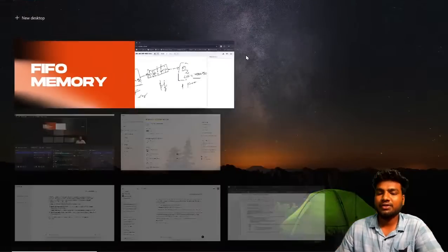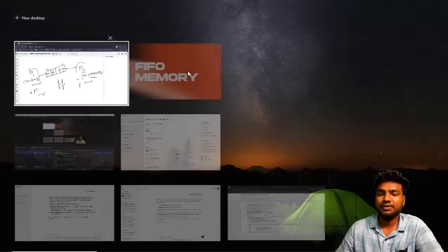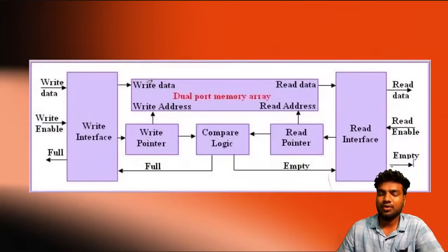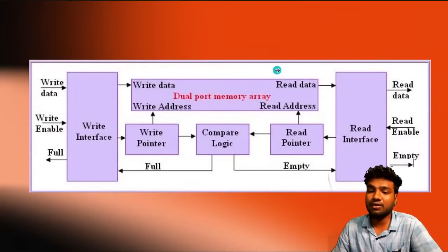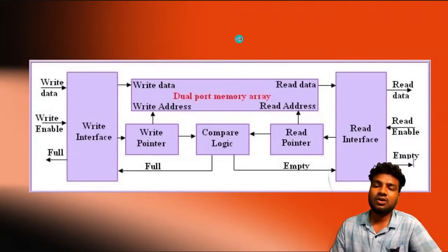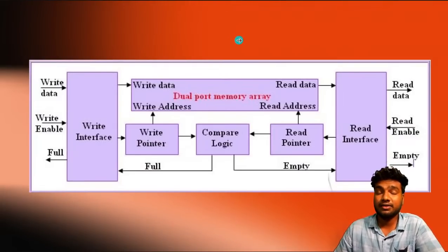So our main signals are for the FIFO. If you are going to write it, firstly we have to be aware of the signals. So the first signal is clock and reset. Based on the clock edge only, it can write into memory, or read, or go full. Anything will happen based on the clock only. So the FIFO will work only based on the clock.